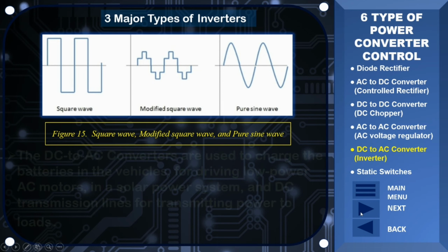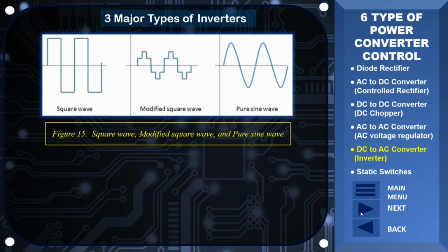Third, square wave. A square wave is very simple. With a DC supply, you switch between positive and negative. There are very few, but the cheapest inverters are square wave. A square wave inverter will run simple things like tools with a universal motor without a problem, but not much else. A lot of equipment will work well on modified sine wave inverters including motors, household appliances, and other items. Some types of load can be problematic and do require sine wave converters.